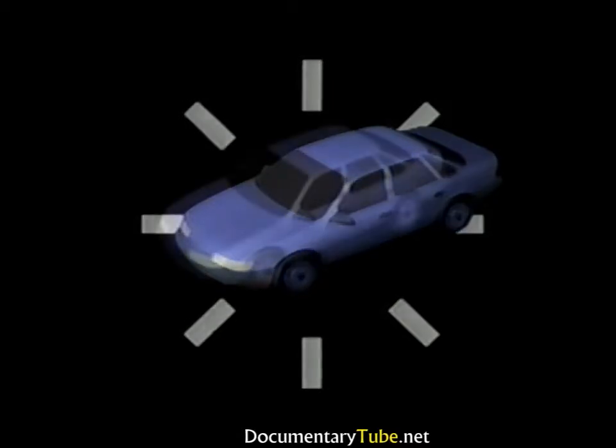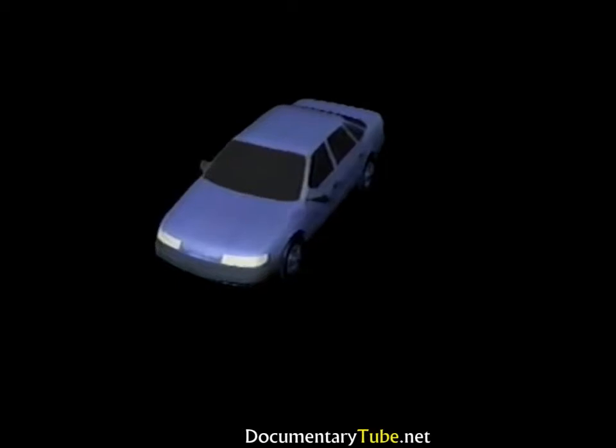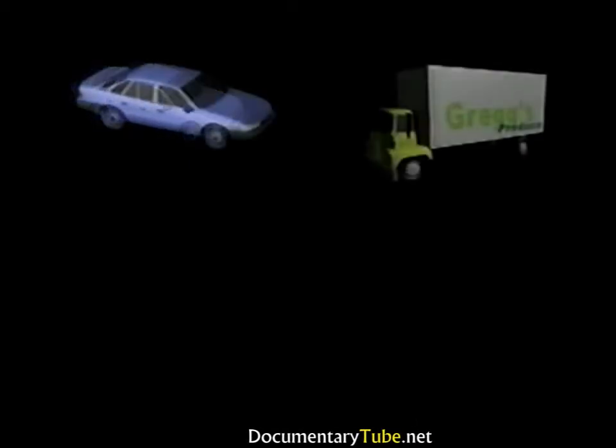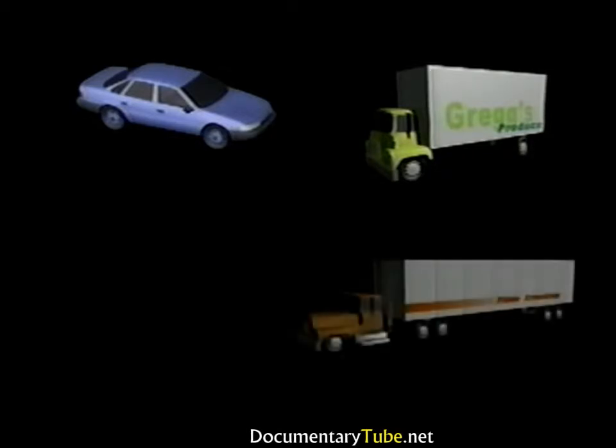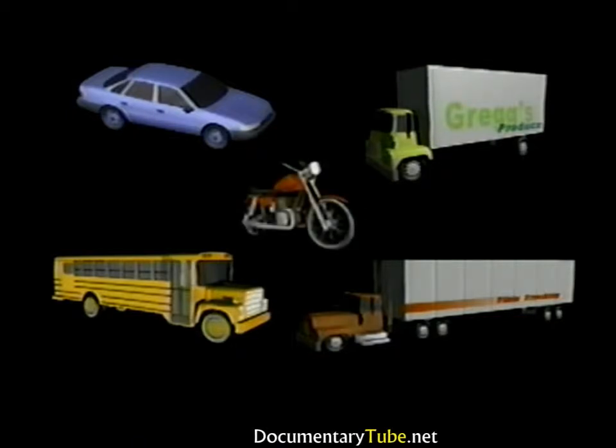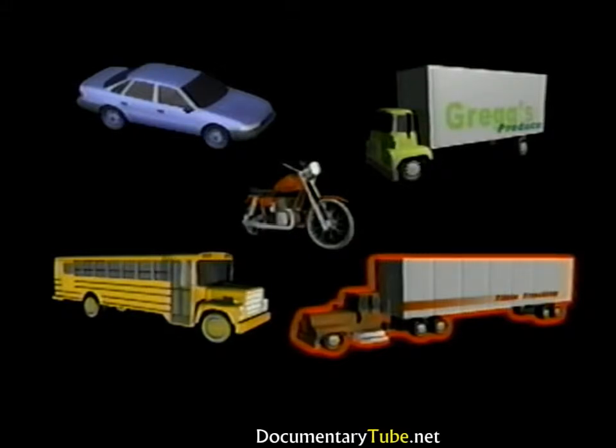Vehicles are typically divided into these categories: automobiles, which includes all vehicles having 2 axles and 4 tires, designated primarily for transportation of 9 or fewer passengers or for transportation of cargo. Medium trucks, which includes all cargo vehicles with 2 axles and 6 tires. Heavy trucks, which includes all cargo vehicles with 3 or more axles. Buses, which includes all vehicles having 2 or 3 axles and are designated for transportation of 9 or more passengers. And motorcycles, which includes all vehicles with 2 or 3 tires with an open-air driver and/or passenger compartment.